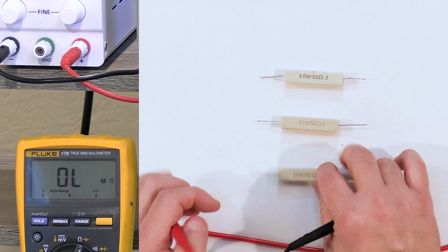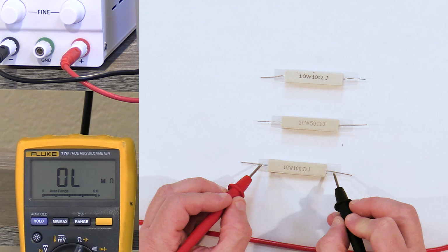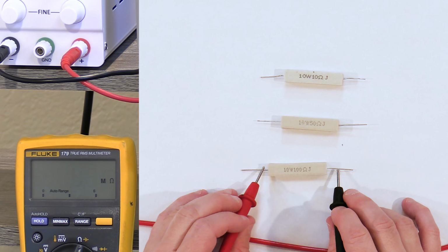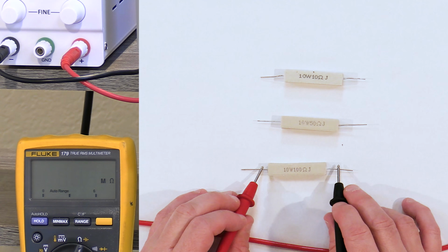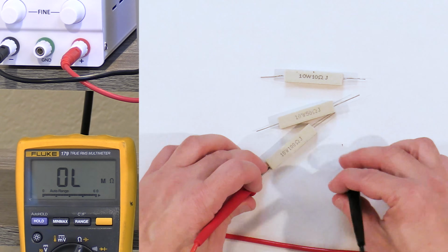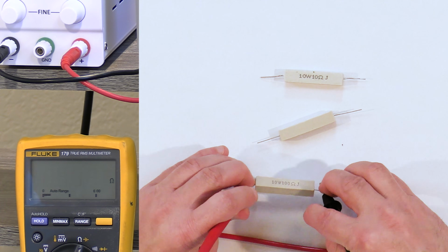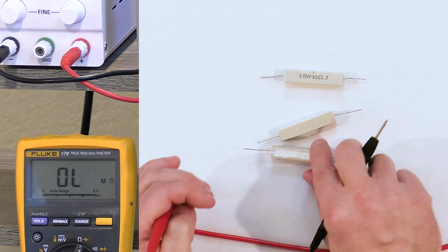But keep in mind that as I'm pushing on it here at the contact point with the probes and the wire, there is a small resistance there. The more I push, the better it is. If I just push a little bit, you can see it's going to read 99, well, that's actually pretty good. But if I push just a tiny bit, it's going to jump around. It's not going to be very accurate. But if I push hard and get a very low contact resistance or high contact pressure, then I can see it's not 100, it's 98.9.